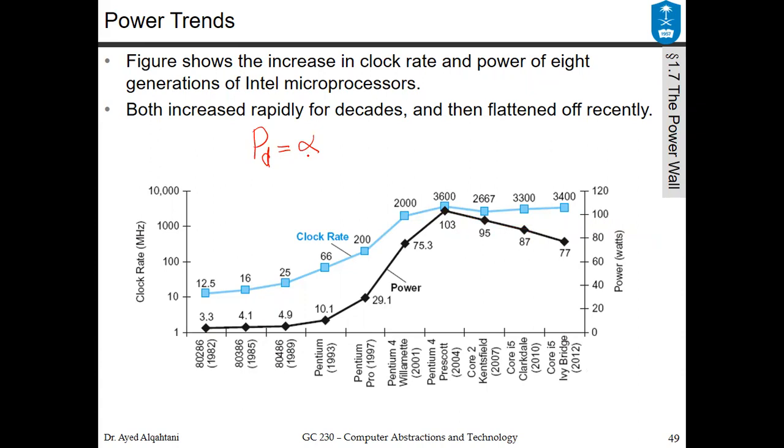It measures how dynamic this integrated circuit or this design is, how much it is switching. This is alpha times the capacitance times the voltage squared times the frequency, and that's what we care about here. Anyway, here's the relation between the power and the frequency. The more frequency you want means that you need to increase the power.